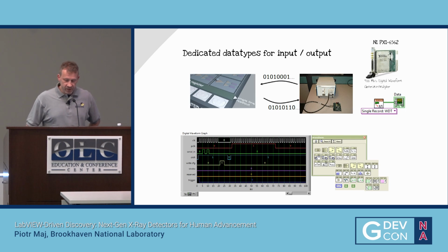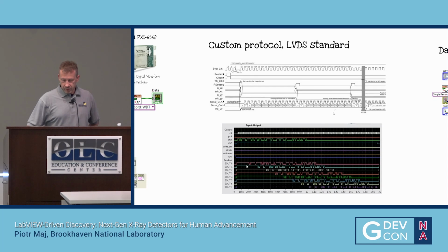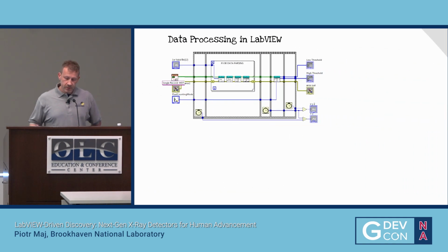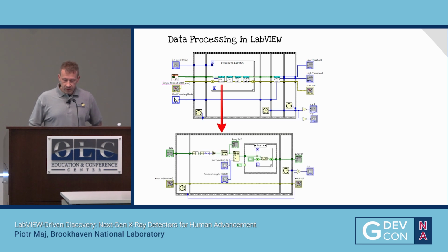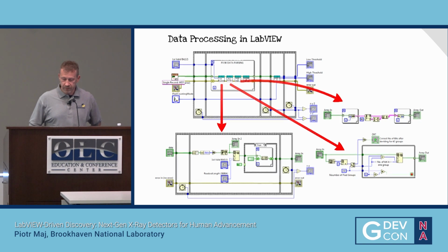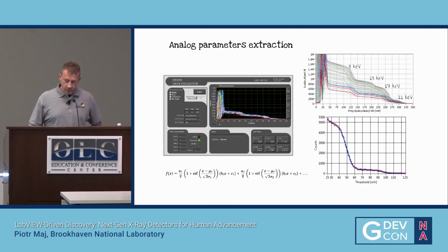function that performs the acquisition from waveform generator analyzer. You can see your protocol right there. You can just inspect visually if everything works fine or something's wrong. And then, from this bit stream, which is extremely scrambled at some point, we need to extract the analog values. And LabVIEW has options for that. It gives us all the necessary functions to work on digital bit stream, binary waveforms, transfer to numeric waveforms, and eventually show it on the user interface.